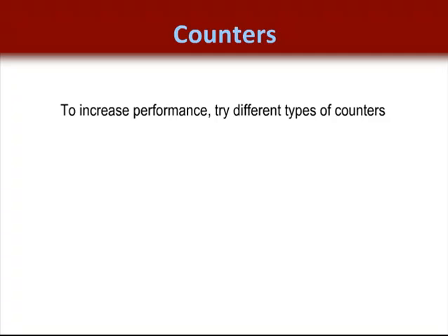Most customers don't spend any time comparing the carry logic implementation with other counter types. Using counters of any of these types can save resources or run even faster than a carry logic implementation. While these counters are not used very often, if you are running out of resources or having a timing critical path that passes through a carry chain, you might want to consider one of these other implementations. However, it will take extra time to construct one of these counters in your HDL.